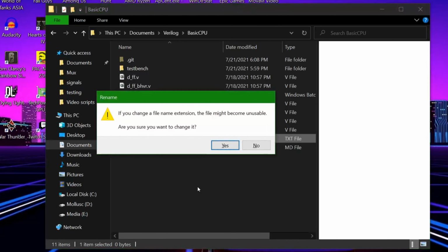In-out ports should be treated like wires and should therefore be continuously assigned. I'll use the ternary operator to assign data. If chip select is 0, output should be tri-stated. If chip select is 1, then output enable should decide. Now in the clocking block, I should have the write logic.